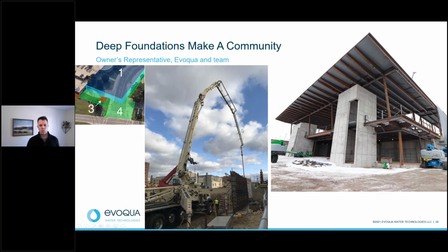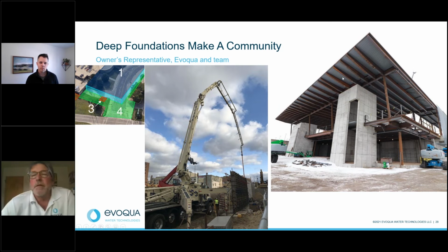And so there was a lot of dewatering that happened in this area. As you can see here, here's our frac tanks. So the water would come in along these pipes. We'd fill these up, come over here to the rest of the system. We have our filtration system here, as well as our kettle tanks that we'd be using. Here's our pump, which would have been right here in the middle of the site. Again, we put piping all through here that came in a giant U around the site and just sucked it up from the key areas.